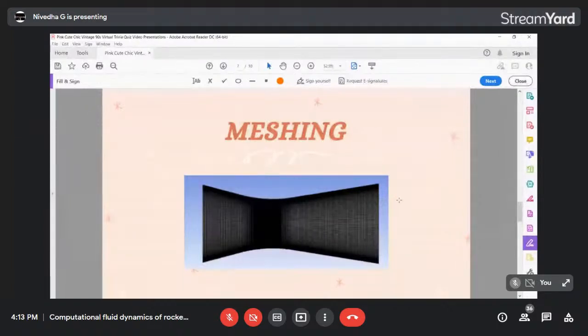At the throat and towards the wall there should always be a thicker or finer mesh because that's where your properties change. As said, at the throat your properties change, and towards the walls there can be viscous effects too. Though here I am playing only with compressed air.